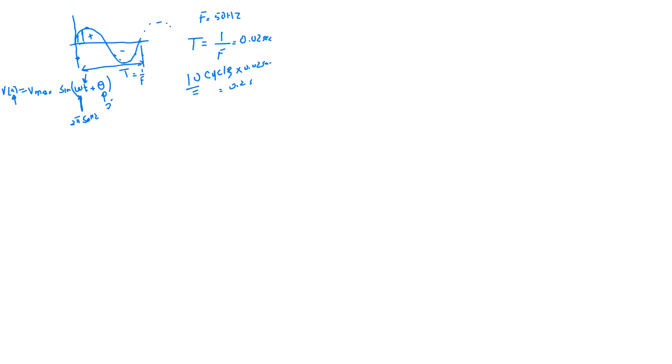So now in time simulation, we don't need 10 seconds, because 10 seconds, 10 times 10, those are like 100 cycles. Yeah, exactly 100 cycles to be displayed in that screen. But we don't need 100 cycles, we need only 10 cycles. So 0.2 is enough, maybe less sometimes. We need 0.1 to display five cycles, and it will be more clear on the window. So instead of 10 seconds, we'll replace that one with 0.2 seconds as time simulation time.